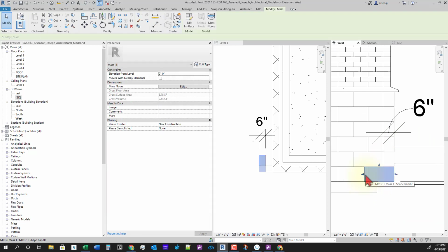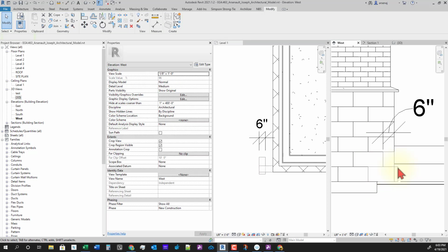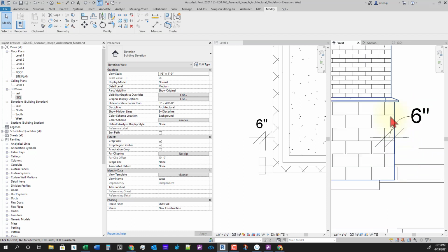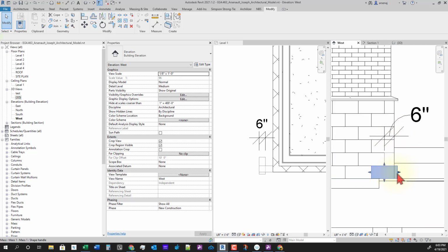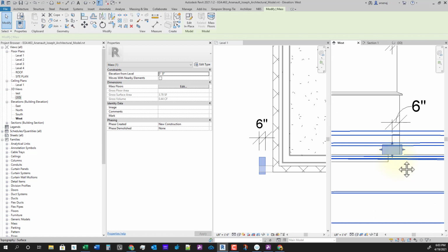And then they'll actually have to cut off about 2 inches of this longer block. But I think that's better than trying to cut them down the middle. So this would be an accurate layout for them to be able to lay out the brick.